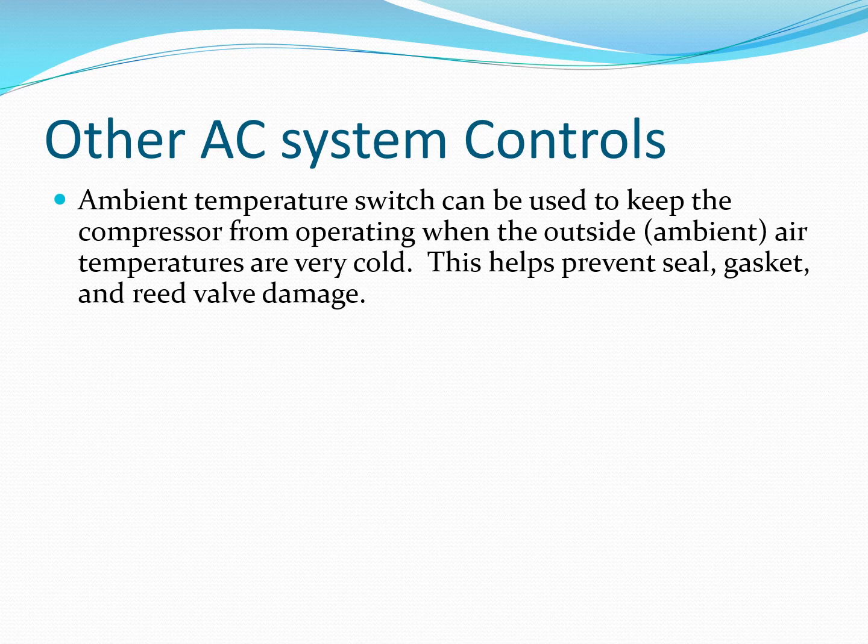However, some of you have already noticed that during the winter time, the air conditioner compressor does cycle when you have your system on defrost. That does two things. It keeps the refrigerant cycling throughout the winter time so that we keep seals moist, we don't dry out seals and cause a leak. And that also helps in humidifying the air. During the winter time, air gets very dry, you have loss of static electricity, so we're using the air conditioning system in the winter time to actually put some humidity into the air that is coming out of the vents.